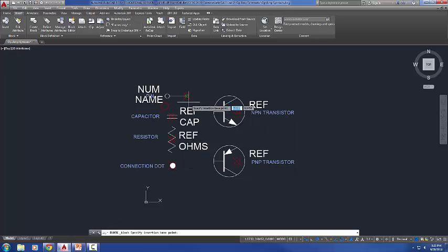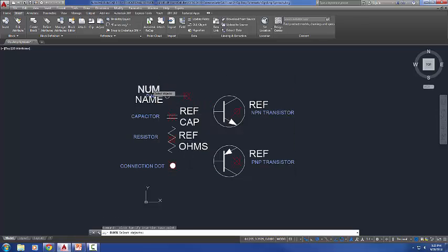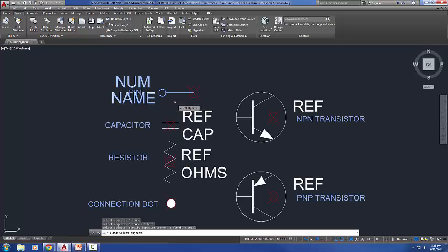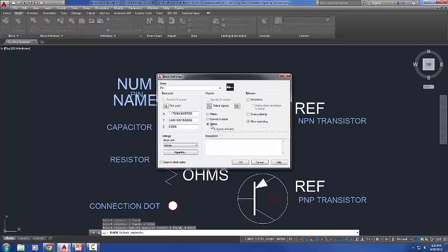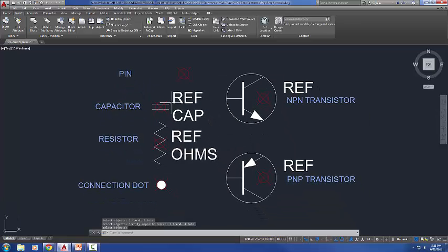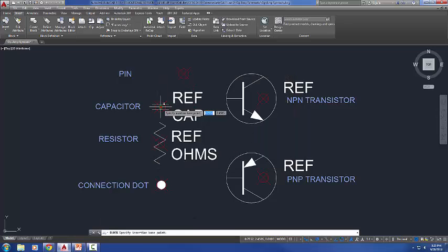I'm going to click this little button right here to define a new boundary. What this boundary is going to do is allow AutoCAD to zoom in when I set this view current. Right now, this black area that you see is what AutoCAD's going to zoom into. I want it to zoom just into that east elevation. So I click that little area. Press enter. And uncheck this. This is very important. Uncheck Save Layer Snapshot with View.